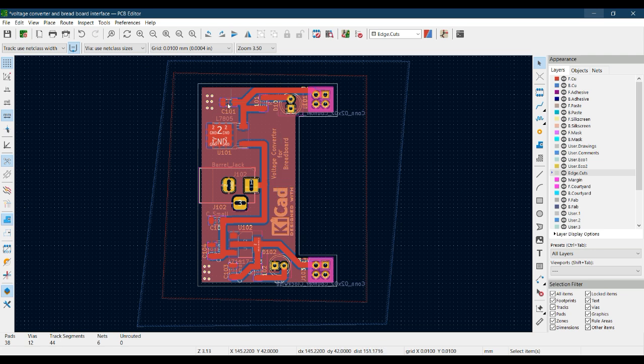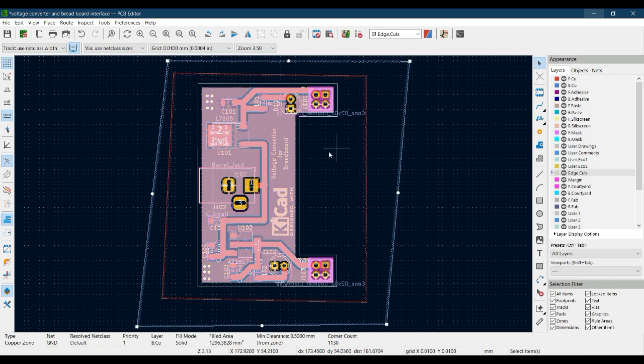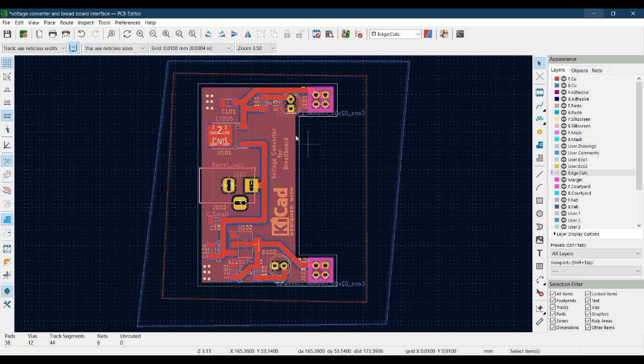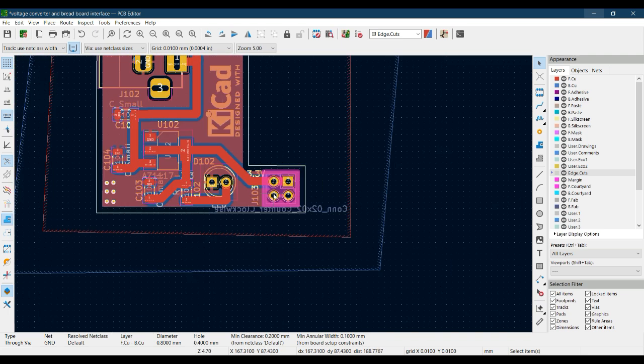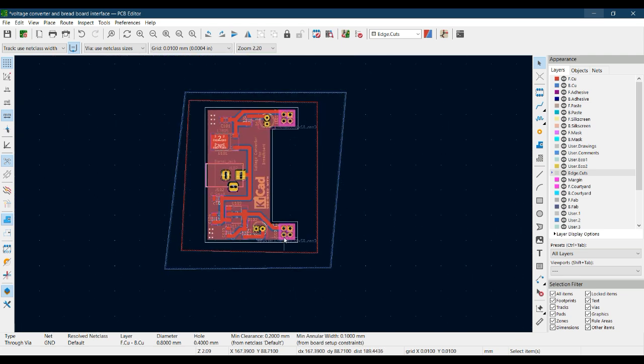After placing our components, we have drawn tracks between them. We have created two fill zones, a front copper fill zone and a bottom copper fill zone, and connected the top and bottom fill zones with the help of these vias, as well as the connector ground pins, because they are through hole. They travel from top to bottom of the PCB.